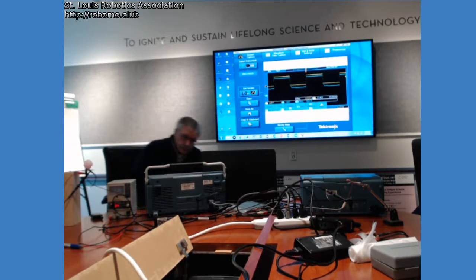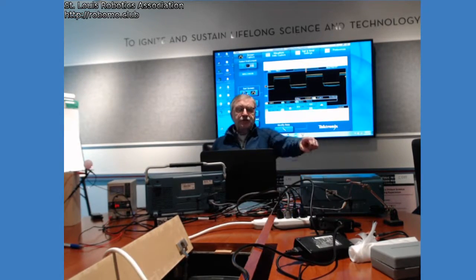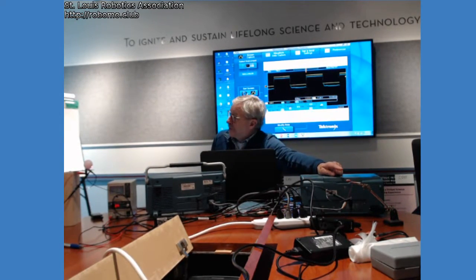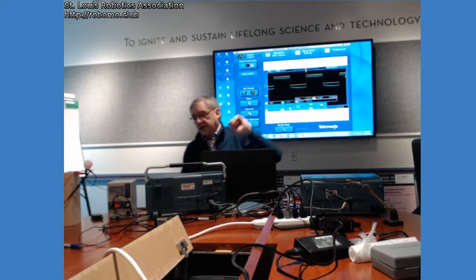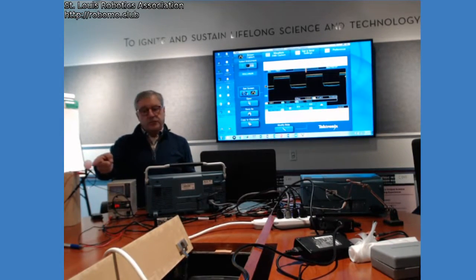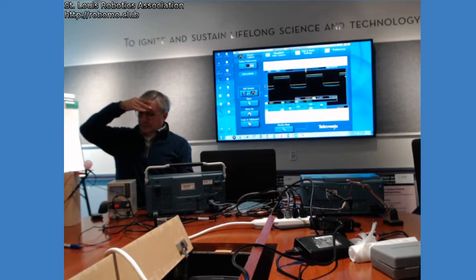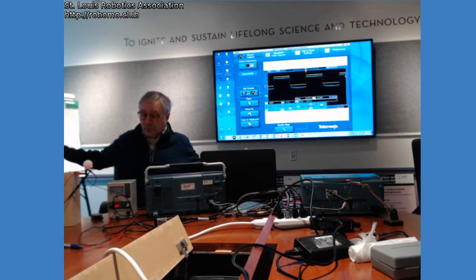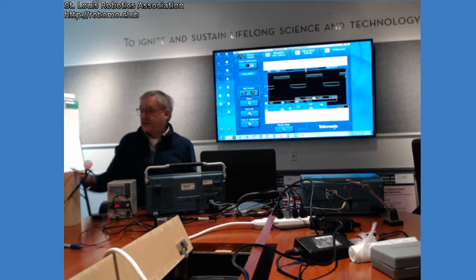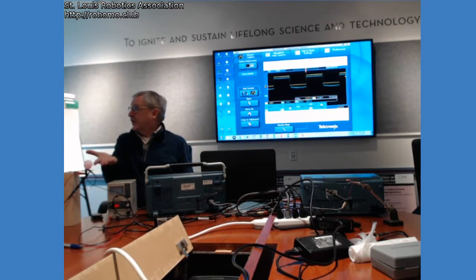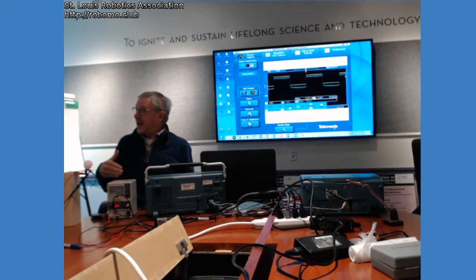I don't know what this one does, but this is the laser that came with the kit. And this is that SFH 203P photodiode, which is a 20-cent photodiode that has the wide field of view. And a 1 meg ohm resistor. In fact, we're getting too much gain out of that 1 meg. We'd be better off with 100K. So we're getting plenty of response here.